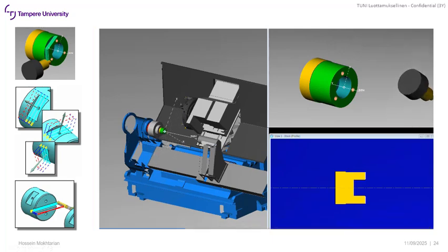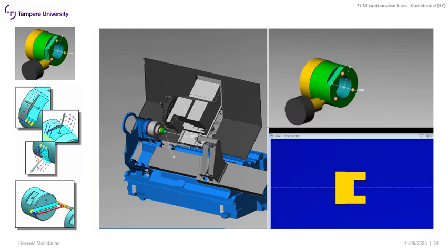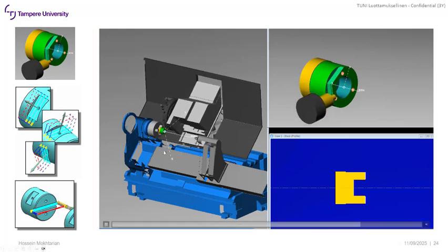So noting that the next one will be moving on to machining the side slots. Note that in this view, on the right, the tool is actually machining the slot on an inclined angle. And on the left side of the view, you can see that it is actually the workpiece that is rotating, and the cutting tool is only moving in a Y direction in the machine that we have in the lab, sliding on the component of the machine itself.